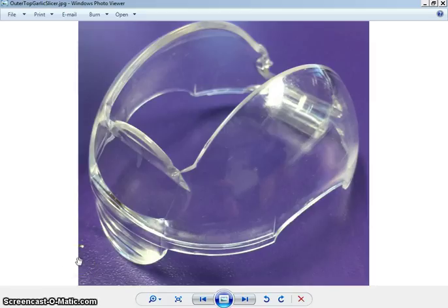So unlike most of the questions that I've been answering, this one actually comes with a part file, and the question is, I'm confused on how to make the details of the part. The curved side, the cylinder on the side, the cuts on the body, it's not working on a curved face. And it's true, it's really hard to make sketches on curved surfaces, and when the entire part is a curved surface, it gets really tricky, but we have to use something called planes.